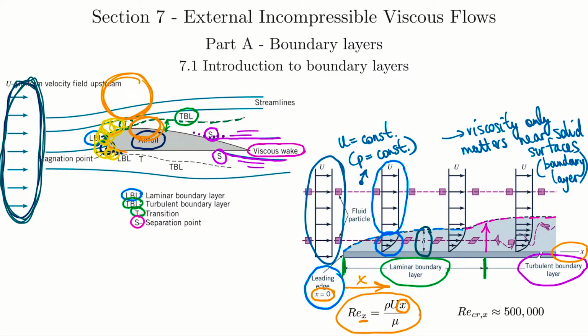It's a slightly different way of thinking about the Reynolds number, but because we're talking about a situation in boundary layers where we're discussing when the viscous effects are important, and we know the Reynolds number is a comparison of viscous and inertial forces, this is another situation where the Reynolds number becomes important. Now, I should mention that every case is different, and these Reynolds numbers will depend quite a bit on things like heat transfer properties or surface roughness.